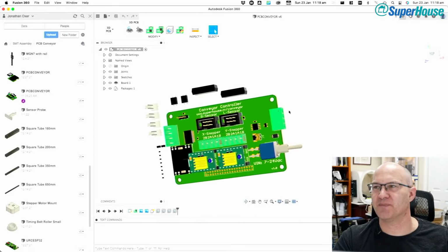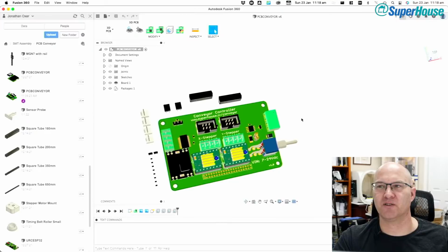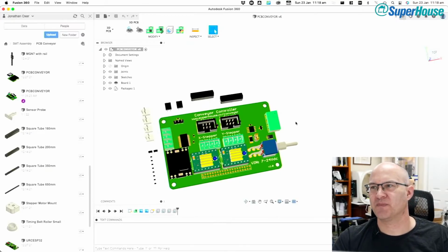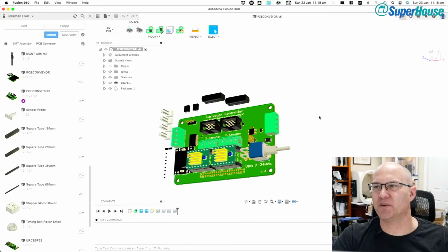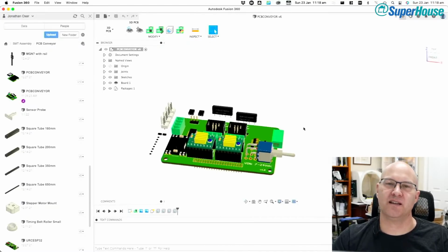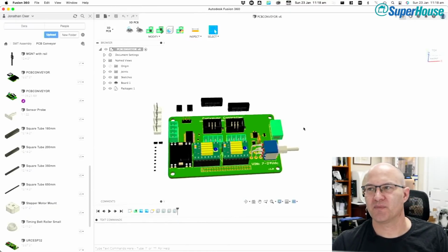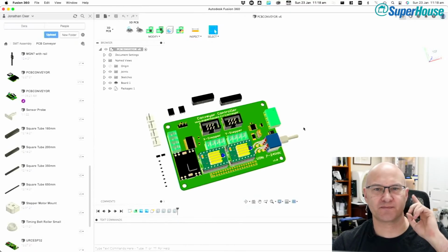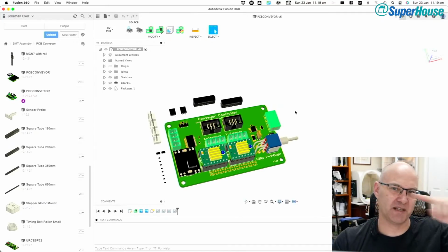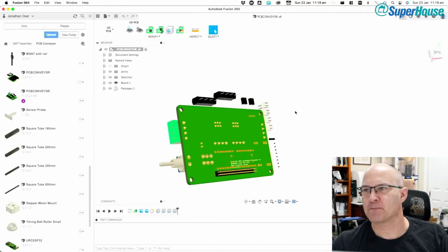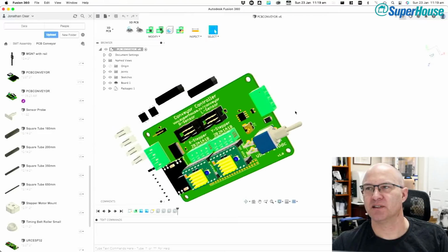So the idea is that a single cable that plugs in here provides power and communication, and it can loop around from one device to the next. They can each have their own identities on the CAN bus, and I can communicate with them. Then at the other end, I could use an Ethernet to CAN bus bridge, and that way one network connection would then connect to all of the devices on the bus all the way down the production line. Right, so I figured that CAN bus would give me the most flexibility.